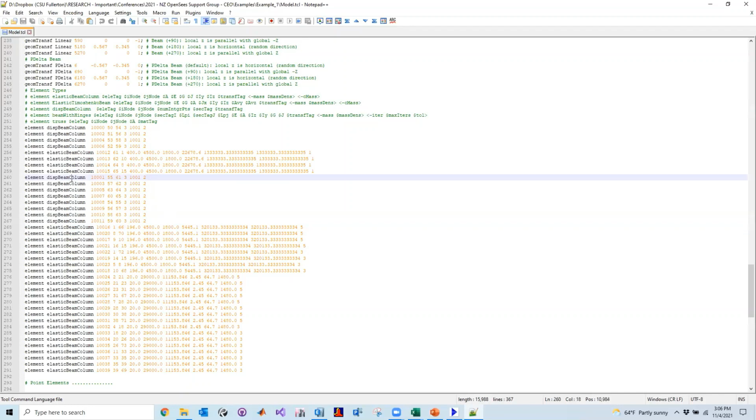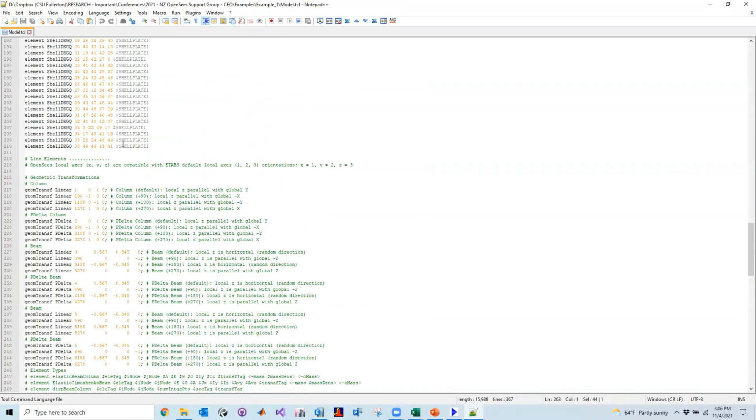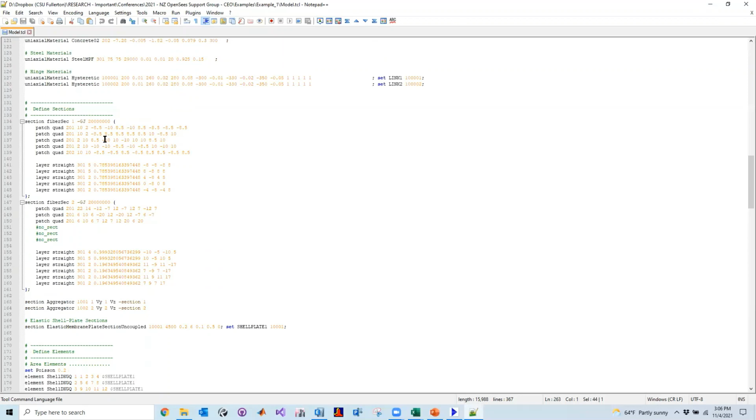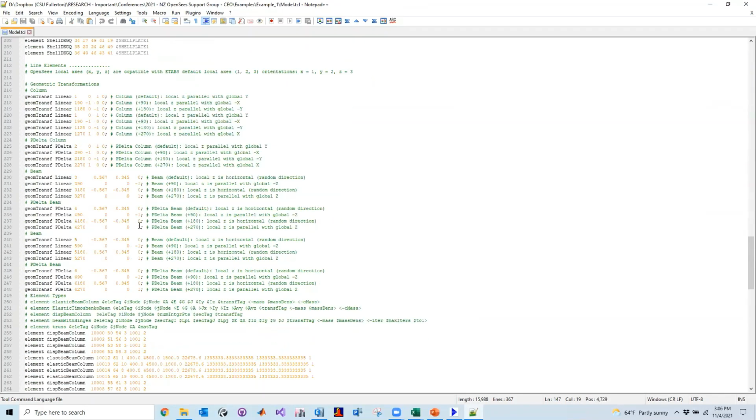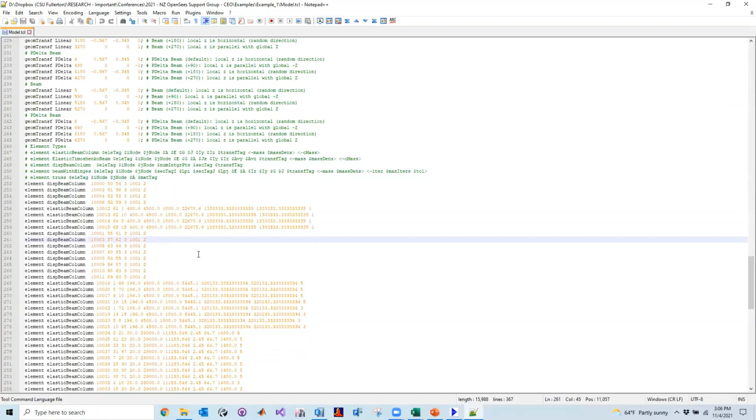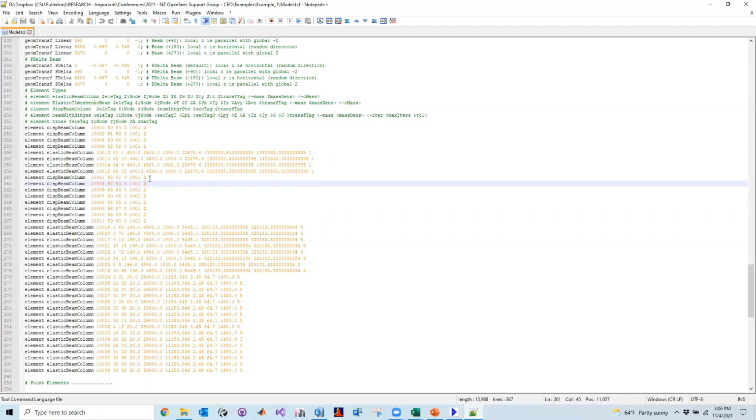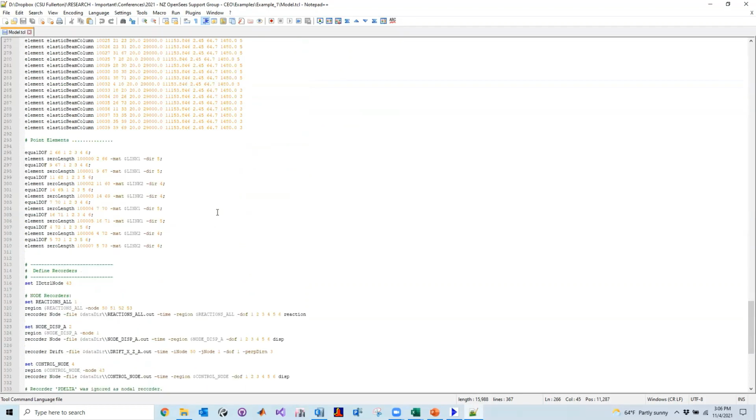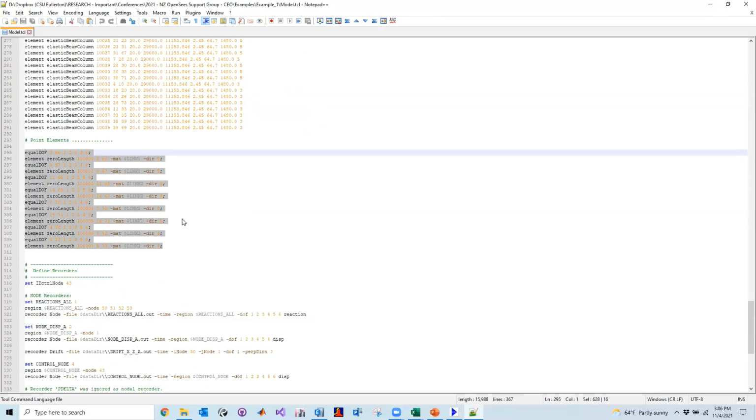And here we have our displacement-based columns, which is basically related to this aggregator tag up here. So fiber section 1, fiber section 2, these are assigned, here's 2. So we are assigning the number 2. We have these hinges, zero length elements, as I said.